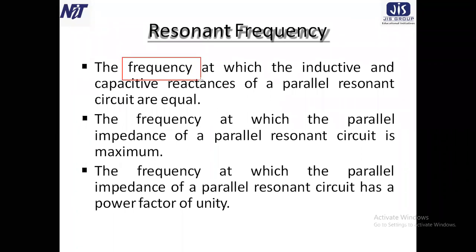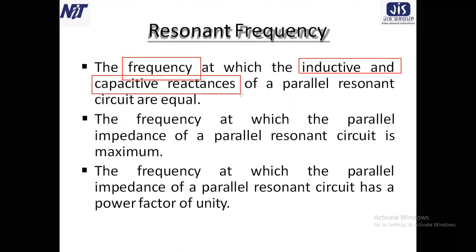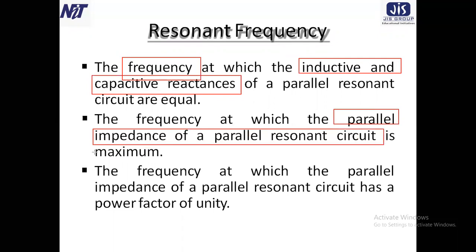This frequency is called the resonant frequency for a parallel circuit: the frequency at which the inductive and capacitive reactances of the parallel resonant circuit are equal; the frequency at which the impedance of the parallel resonant circuit is maximum; and the frequency at which the parallel resonance circuit has a power factor of unity.